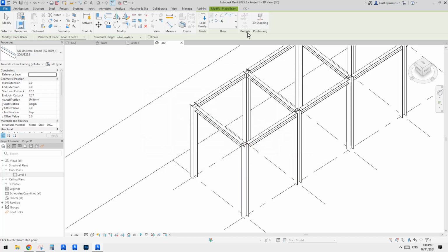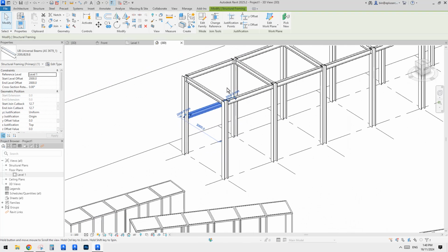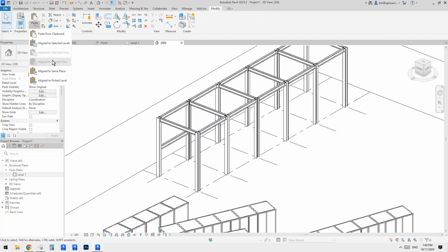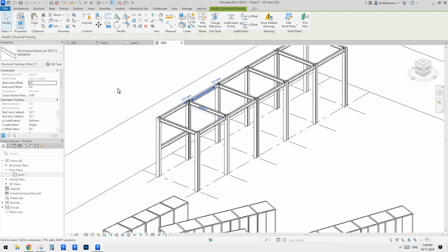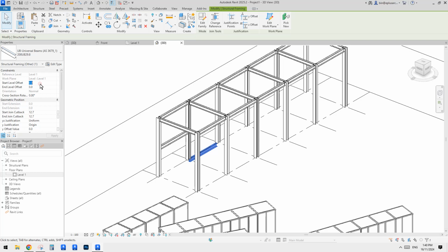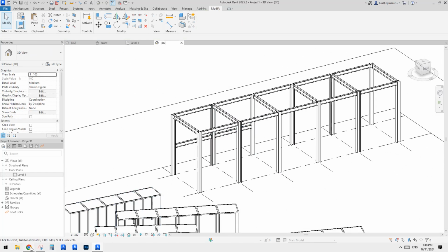So you can also use 3D snapping. This is usually what I do. You can set a level, something like that. Or maybe you can just copy, Control-C, paste in same place, and then change the height or change the level. Edit to level 1 with offset 2 meter, so it will match this one, right? Okay, and then let's have a look again.